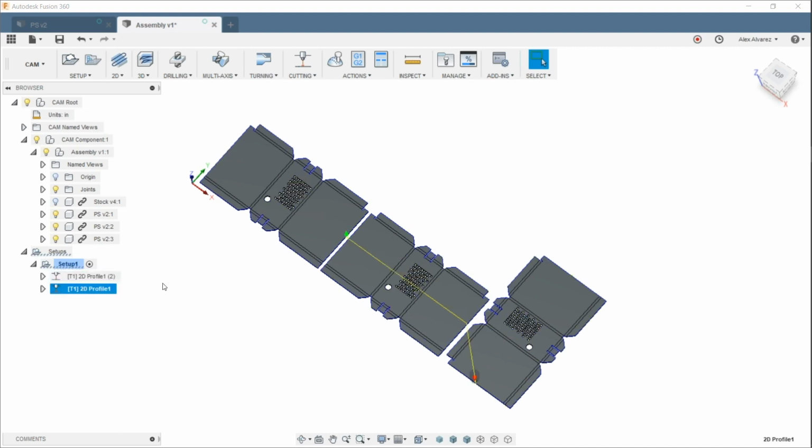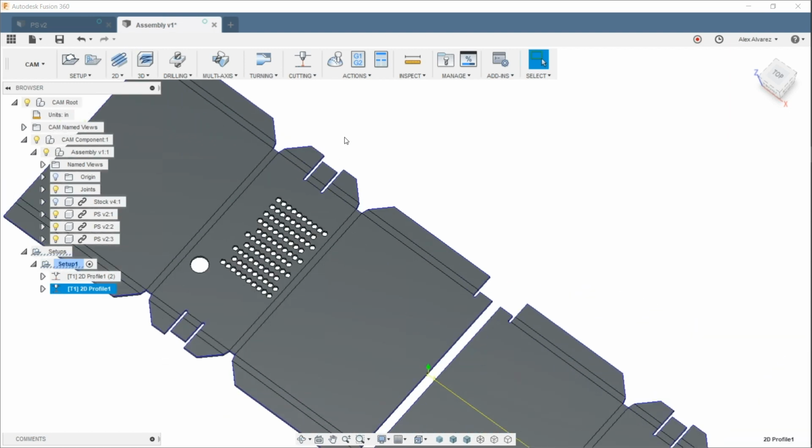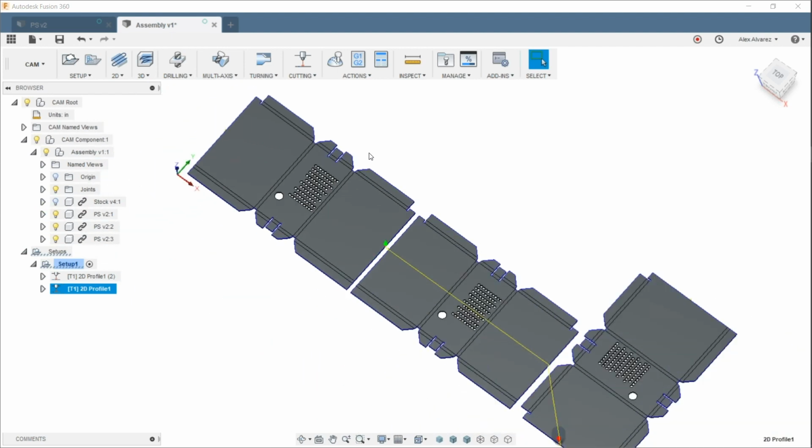So here we can right away see that it automatically regenerated, and it handled that height change without any issues, right? And that's really what we want to focus on and highlight: having a complete CAD CAM package. It's always going to have that reference, and it's always going to be able to link those models that you create. And having that connection to the CAM environment, you can rapidly go in there, regenerate some of the toolpaths, and give you an updated G code for that.